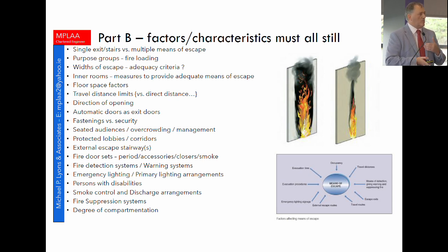In a performance-based design, you've got to identify the fire load for every single room, and where you're leading to is how fast will that fire in a room turn into a flashed over fire? And will it, based on your fire safety strategy, will the flashover be controlled by a sprinkler system or a water mist system or something similar to that? And that's all got to be presented in your design.